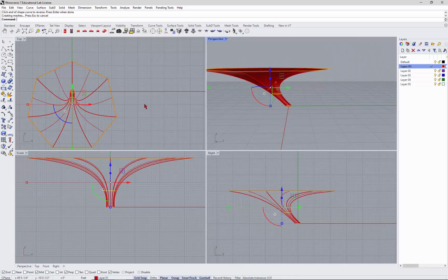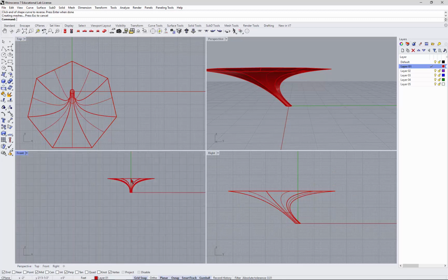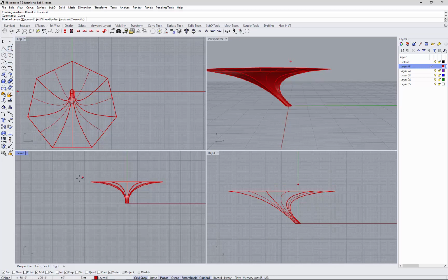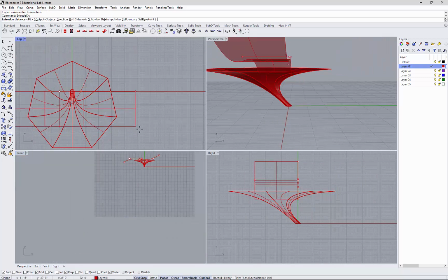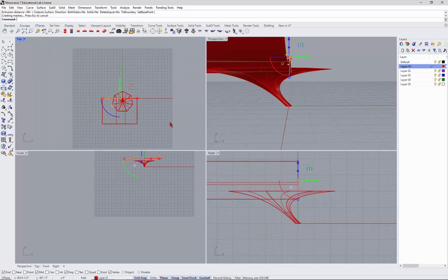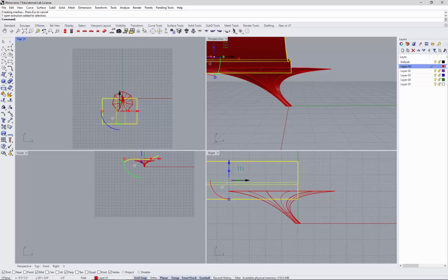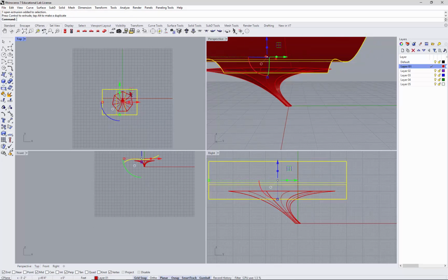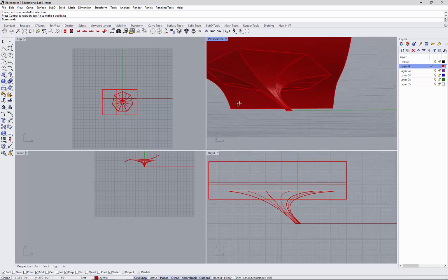The other thing that you can do as well is this is a flat top, right? So I'm going to come into my front view and I'm going to draw a curve. So I'll just draw some kind of curving piece. And then I'm just going to extrude that curve, right? And let's just do it over here, maybe about that much, right? And then I'll pick those guys and move it to where it corresponds over the top of this guy.